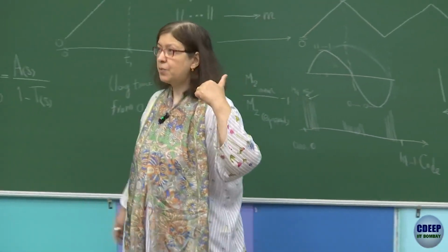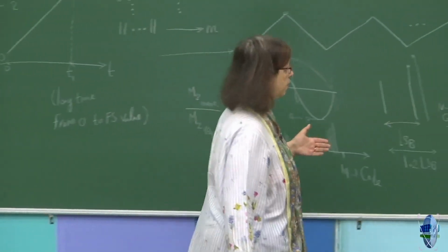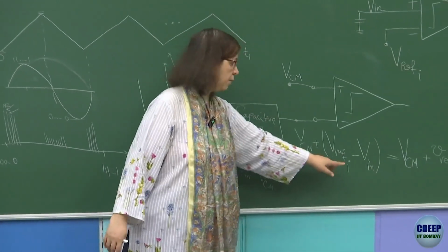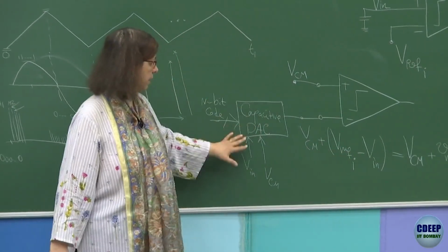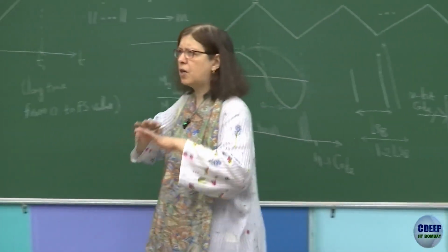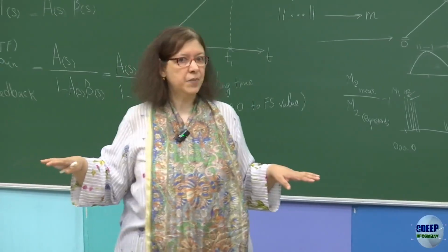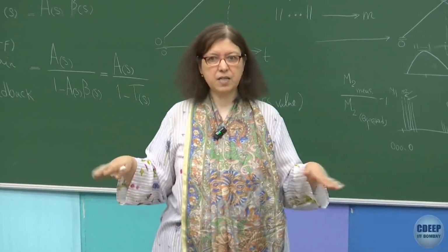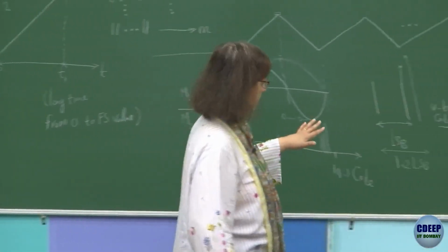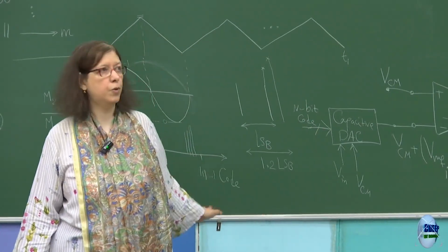For the digital input, it is like a DAC. Therefore, digital code will be converted to the corresponding reference values. While Vin will be like a bias, like VCM, stored on all the capacitors and constant over all conversion cycles. So suppose we have n bits, for example 4 bits, so 4 cycles, Vin remains constant. It's a hold mode eventually.